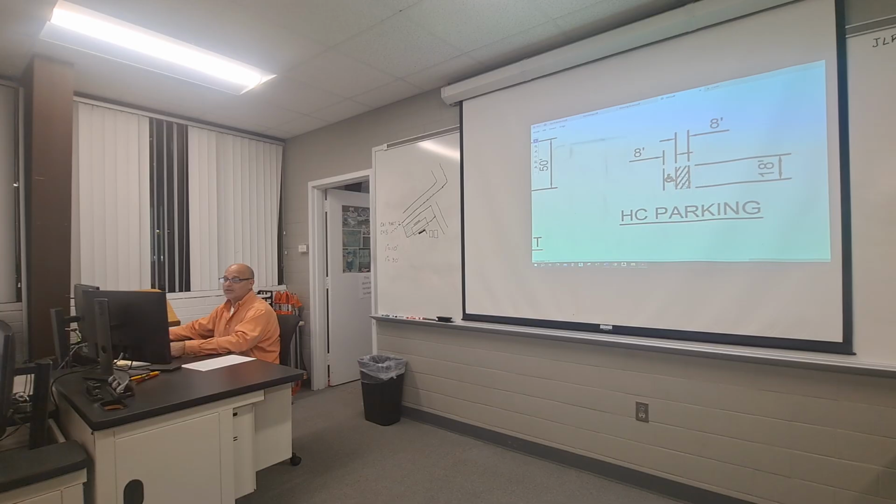Right. So on this one, on the left-hand side, this is the actual vehicle parking area. You can see that this is one handicap space. Each one of these spaces is 8 foot wide. Remember, all of this is gonna be done in a thin line weight. This is not in your object layer, this is paint on the parking lot. Each one of these 2 spaces is 8 foot wide, 18 foot deep. The one on the left is for the vehicle to park at. You will need to put a handicap symbol on that side. The one on the right is for van accessible. You will need to show those lines to illustrate that that is not a parking space, that is a handicap van accessible area. All right, so everybody clear on that?